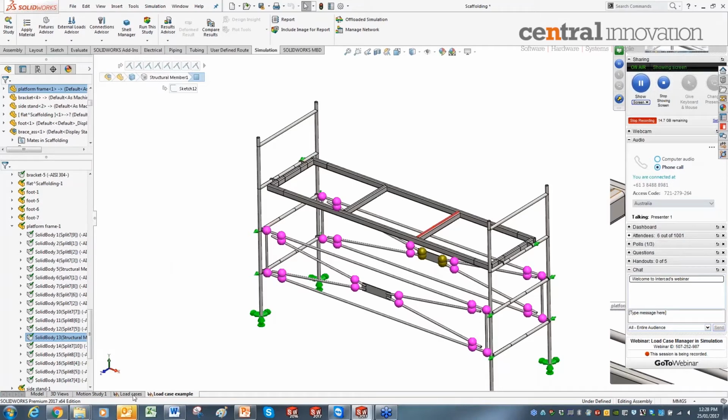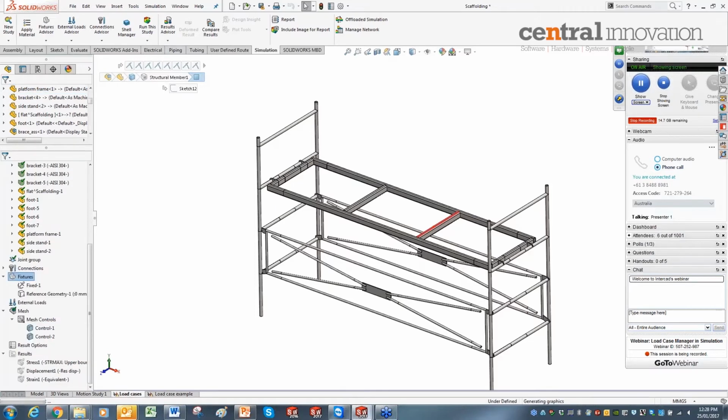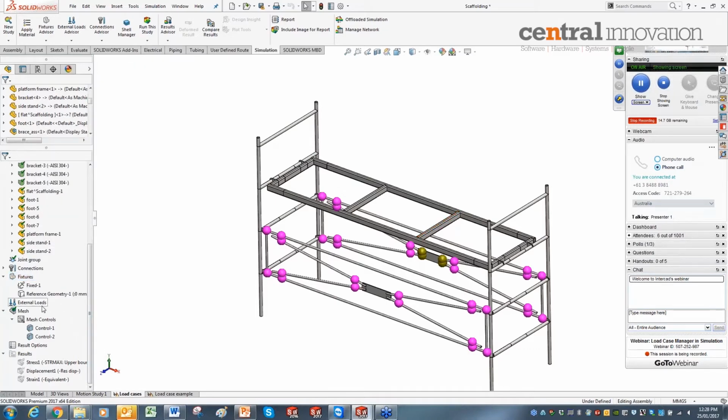I'm going to make use of force to constrain that vertical displacement of this beam. So again, the loads are applied in the predefined setup. I'll copy it and then edit and show you how the load is defined. It's loading the predefined study. Now, because the mesh in that setup is a bit dense, that's why it takes time to load. So I'm going to copy this external loads. Okay, I have to define the external loads. So I'll show you how to define the external loads.